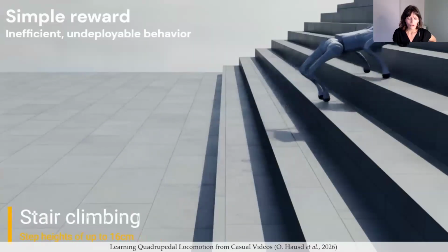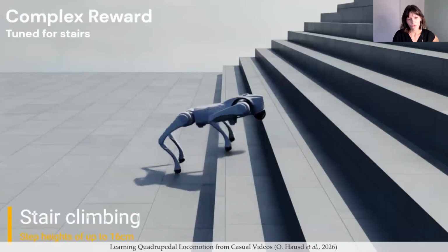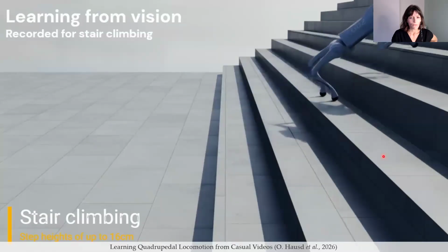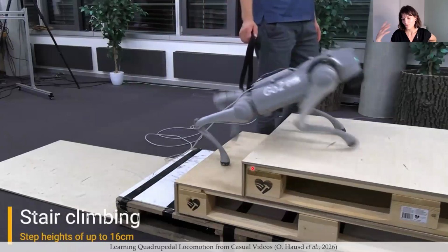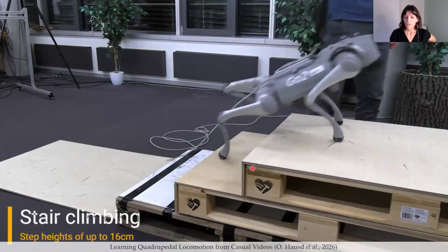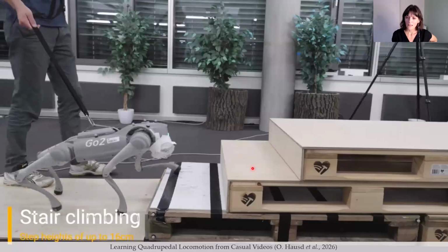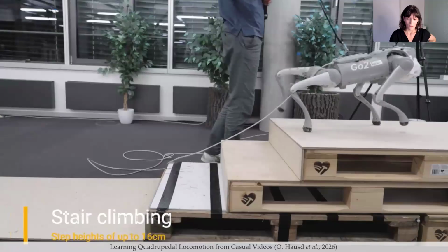Similarly, here we show that various other methods take quite some time or a lot of reward tuning to get good results, while by recording a dog climbing stairs, we can use that as a prior, similar to what Ryan and Aaron showed for humanoids. We can learn from 2D videos. So this is a combination of real-world data, but 2D videos, which don't include the real physics, plus a good simulation engine in the background that allows us to do RL in simulation and bridge to the real world.